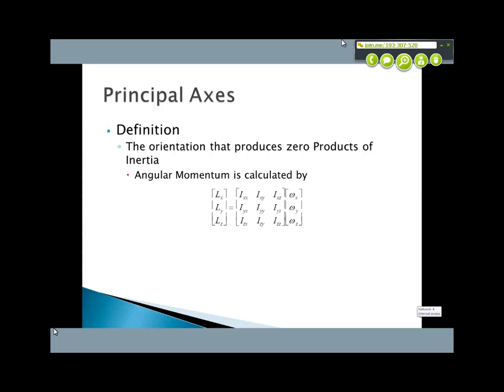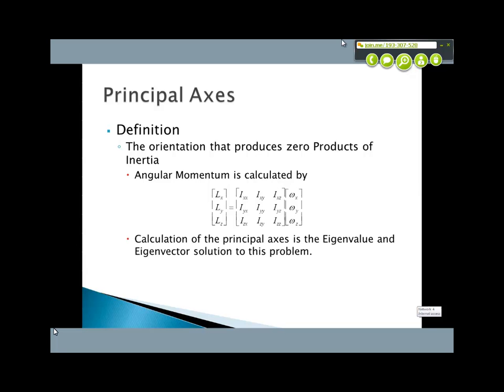The way that you typically solve for the principal axes, which again they do in the calculus math courses and in some of our physics and engineering classes, is they set up the angular momentum equation, and in coming up with the characteristic equation, which is basically developing an equation along the diagonal of this matrix, they then solve that characteristic equation both for the values as well as the vectors that drive this system, so that it's basically values strictly down the IXX, IYY, and IZZ, the diagonal terms of that tensor.